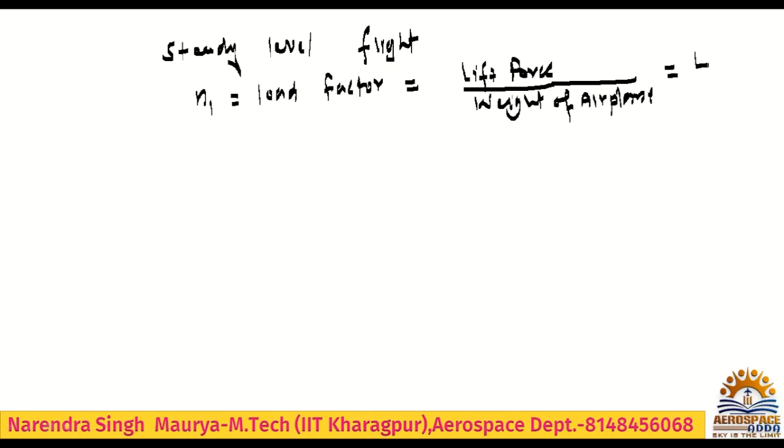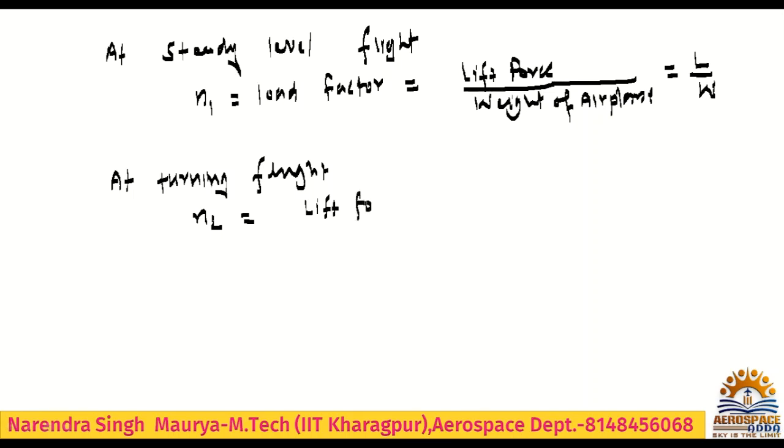So in steady level condition, L by W is the load factor. At turning, because they are asking for a comparison of load factor during steady level flight and turning flight, the load factor is N2, which is again lift force divided by weight of the airplane.